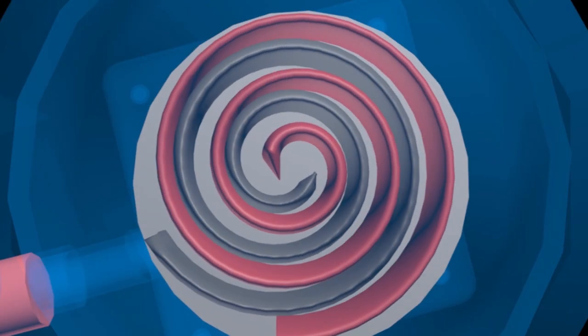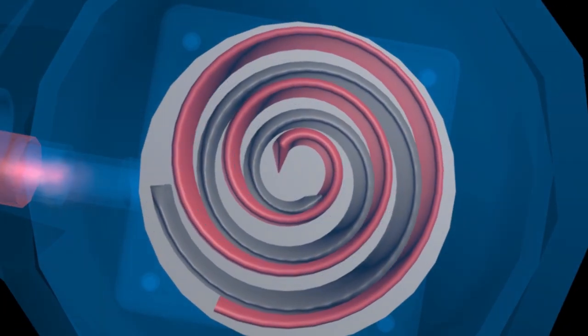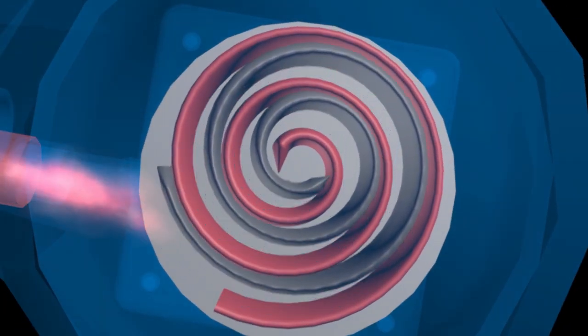The scroll compressor works as follows: gas at low pressure and temperature enters the suction line and goes into the compressor. The low pressure and temperature gas is pressurized by the scroll compressor to high pressure and temperature gas. The high pressure and temperature gas is then passed through the discharge line and goes into the condenser.